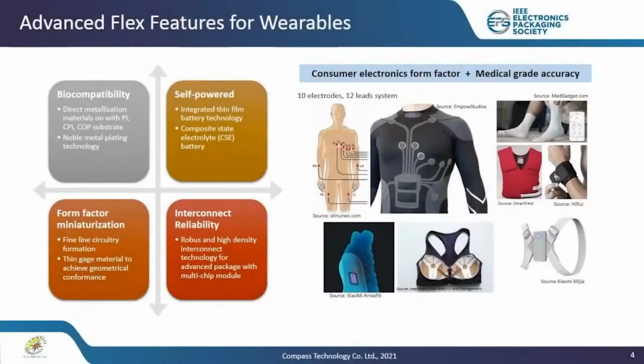If we talk about the challenges of smart wearable devices on flexible electronics, there are a couple of areas we need to stay focused on. First is biocompatibility for direct skin contact and implant devices. Whether the device is able to withstand corrosion or chemicals, or the electrode material can be more sustainable and become washable and durable.